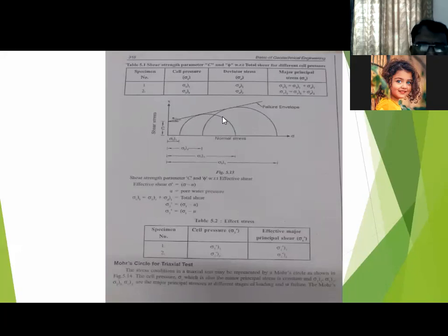कि कैसा बनाना मालूम होगा क्या आपको semi circle? देखिए बेटा, sigma 3 मालूम है आपको, sigma 1 मालूम है, ये तो मिल जाता, ये आपको ready-made दिया रहता, इसका बारे में मत सोचो। तो अब यहाँ origin से ये पहला first specimen के लिए बना रहा हूं मैं, ये ले लो आप sigma 3, और यहीं से आप यहां तक sigma 1 ले लो, ले लिए। अब ये 2 जो point है इनका center ढूंढो, और वहां पर आपका compass रख के या radius लेके circle बनाओ.